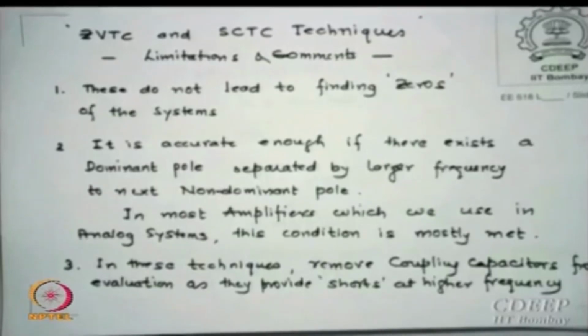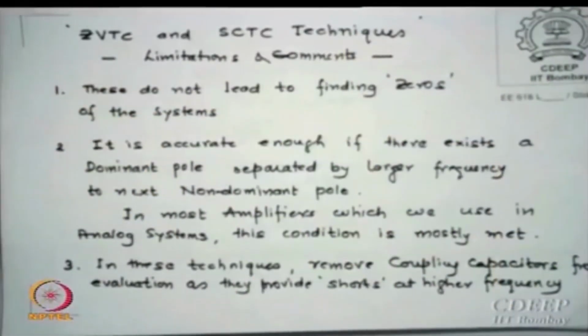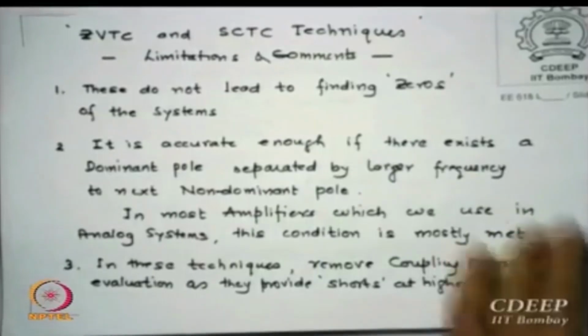So leave that whenever you calculate the bandwidth of any amplifier. Omega P1, or P1, is called the bandwidth of the amplifier. Is this technique clear? Please remember, these are the designer's way of looking at things. Kirchhoff's law is always true for all circuit people, irrespective of whether you design or not. Is that okay? So on Friday we'll start with op amps.